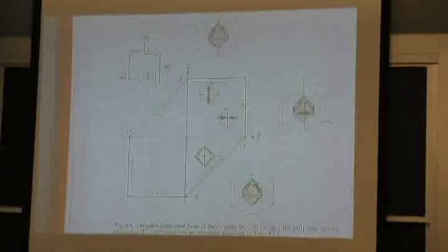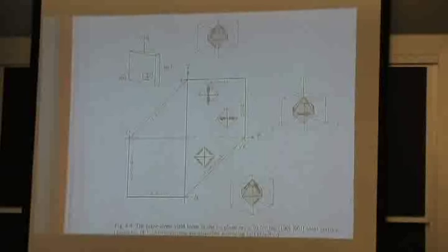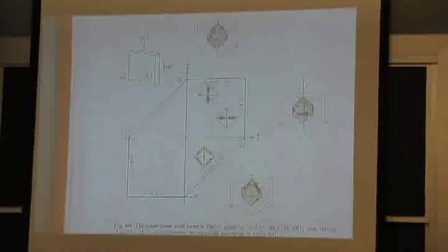And it turns out, for this texture, you just get the Tresca condition. Whether you're pulling here or whether you have a side pull in tension or not, you don't get any effect. You don't introduce anything else. At this point, you actually will have 8 slip systems operating. He calls them 2, 5, 8, and 11, minus 3, minus 6, minus 9, and 12. At that one point, balanced biaxial stress, you would actually have 8 slip systems, and you could get an arbitrary shape change. But anywhere along here, you've only got 4. Anywhere along here, you've only got 4.